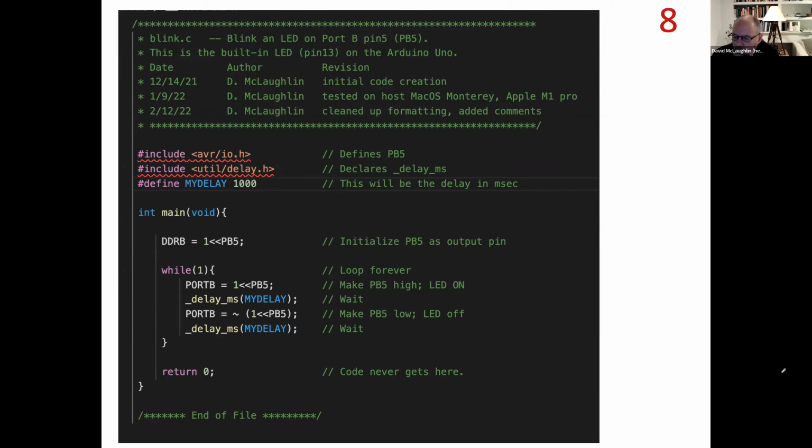Okay, does input value read all the pins at the same time, or can you read one pin at a time? The compilers that we're using to turn C code into machine code will only allow you to access these registers a byte at a time. If you wrote assembly language, you could access each individual bit. When we write a value to port A, port B, or port C, it configures all of the bits in there. Likewise, if we read pin A, pin B, or pin C, it'll simultaneously read all the values from those pins. I'm going to show you how we twiddle individual bits, even though we're reading and writing to all bits at once.